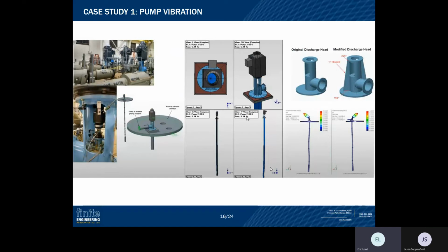And so in that case, what was done here is that some gusseting or ribs were added in the upper right-hand corner here to change that natural frequency. And so we could see what the frequency change is. As a result, you can say, yes, it's near or away from the excitation frequency. And this then relieves it of, let's say in this case, any fatigue issues.